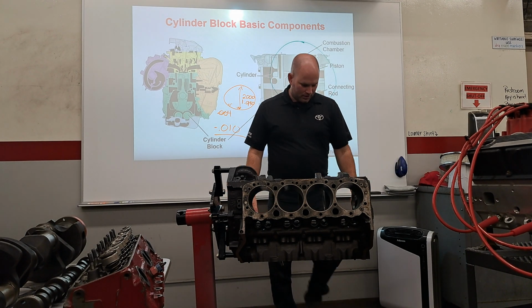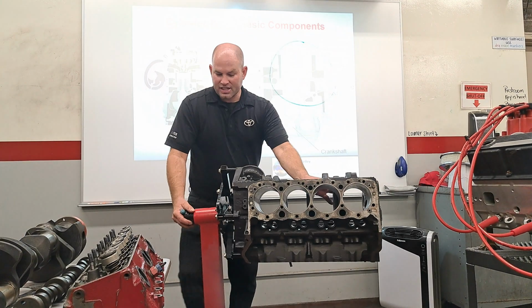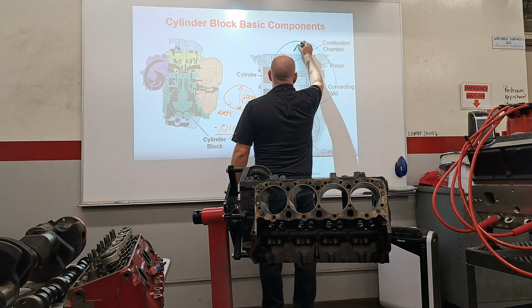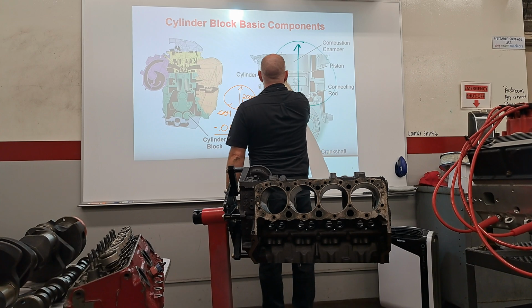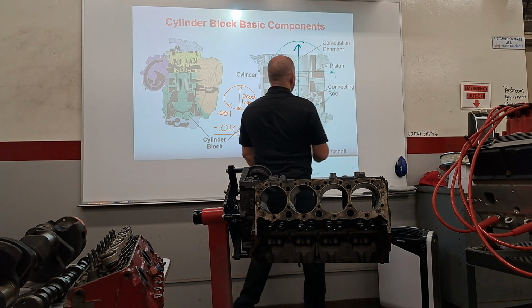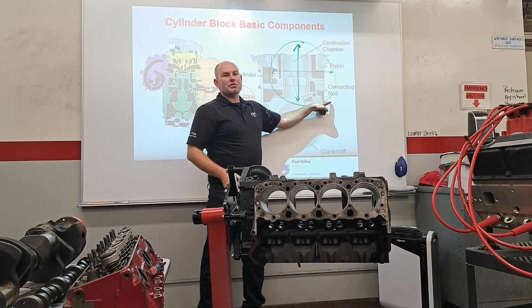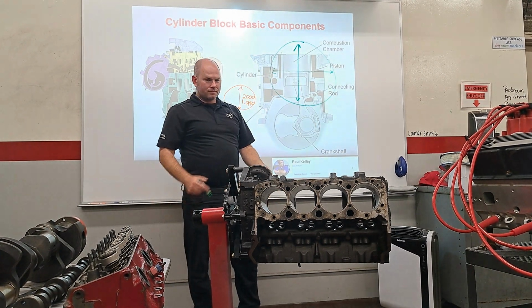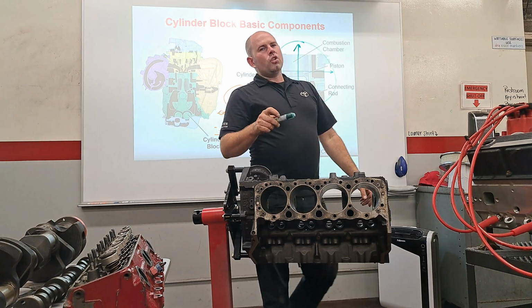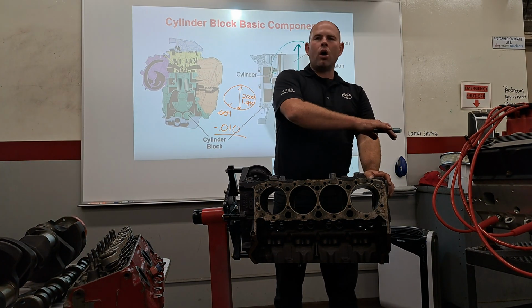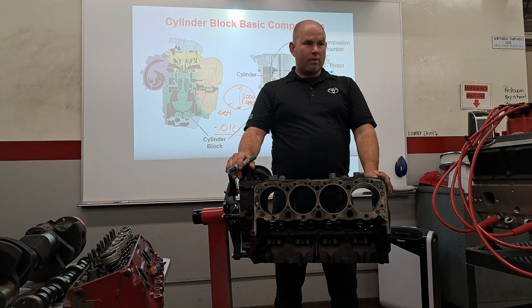Yeah, just like a drum. Exactly like a drum. You have to measure this way and this way. And they should be the same, but as you can see, this one's longer, huh? We've got a little bulge right here. Use the tool that has like those two little rods, right? You can use the telescoping gauges, but we're going to cover all how to measure it when we actually measure them. For now, I just want you to know concepts.